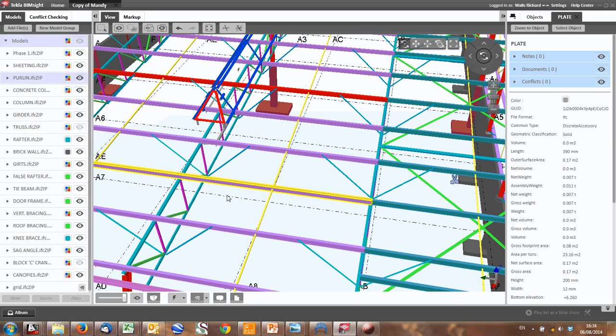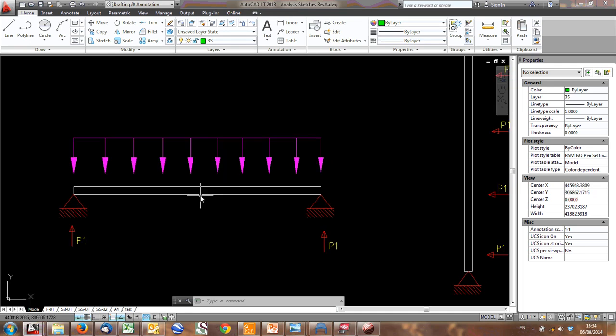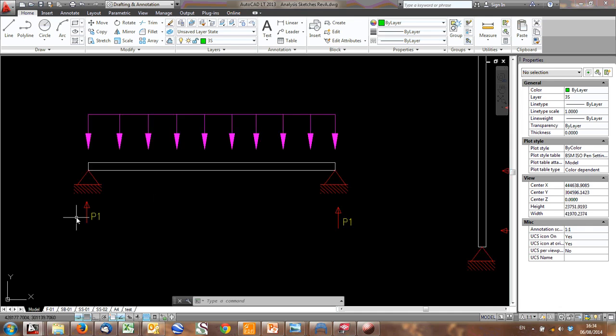Once you've analyzed it, then you can size it. You can size it for deflection. You can very quickly get the I required, the second moment of area required to give you a specific deflection limit, whether it's length over 180 or 250 or whatever deflection requirement that you require in your code. You can size it and then check for strength. In steel, it's often deflection governed, and then you check for strength. But now we design it and it gets reaction.